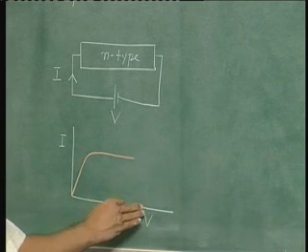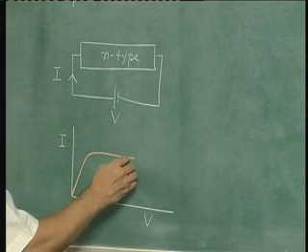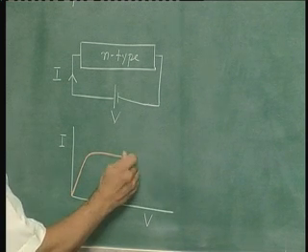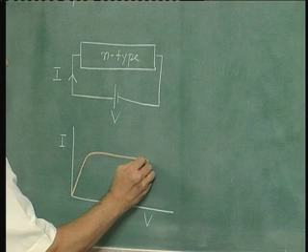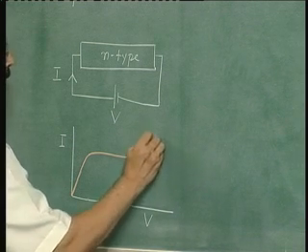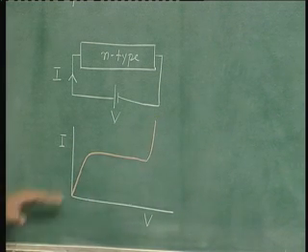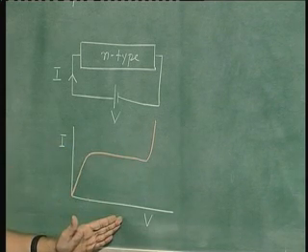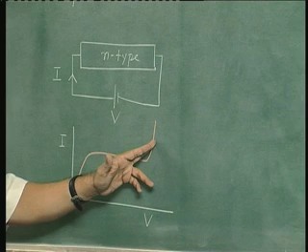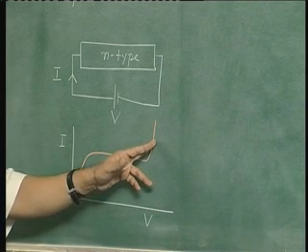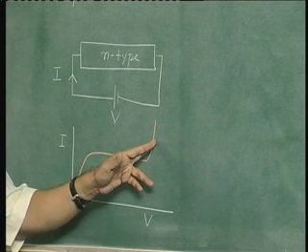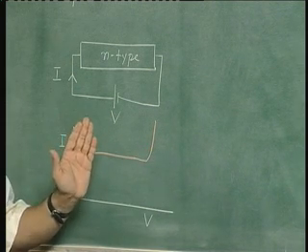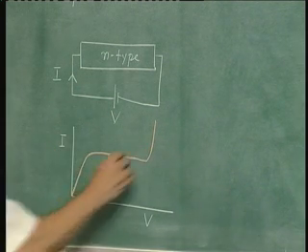If you increase the voltage further in this saturation region, it is found that beyond a critical voltage which is very high, the current starts rapidly increasing again. Now, since the velocity of carriers has saturated in this range of voltages, the increase in current here can only be attributed to an increase in the carrier concentration, because the current depends on the carrier concentration and the velocity.